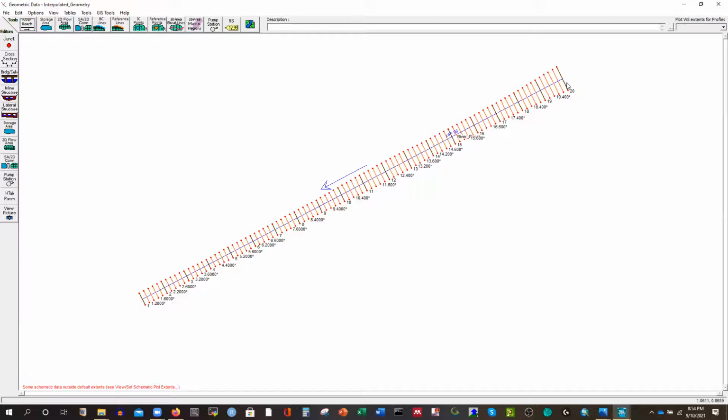There we have to provide the flow rate, the discharge, and at the downstream level at 1 we have to provide the water level. Then the model will understand, okay, this is the discharge here, the very upstream, and that is the water level. So it will keep that in mind, and then it will solve the differential equation, and then it will give us the water level, velocity, and flow rate, everything right at each of these cross sections.